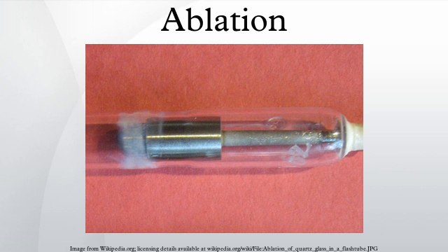Marine surface coatings, anti-fouling paints and other related coatings are routinely used to prevent the buildup of microorganisms and other animals, such as barnacles, on the bottom hull surfaces of recreational, commercial and military sea vessels. Ablative paints are often utilized for this purpose to prevent the dilution or deactivation of the anti-fouling agent. Over time, the paint will slowly decompose in the water, exposing fresh anti-fouling compounds on the surface. Engineering the anti-fouling agents and the ablation rate can produce long-lived protection from the deleterious effects of biofouling.